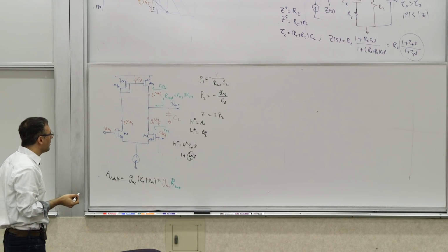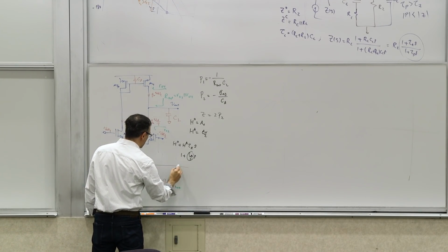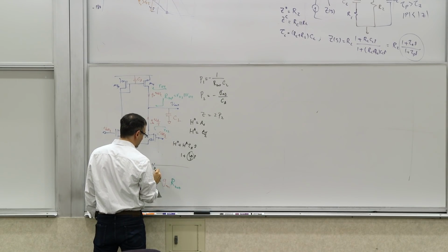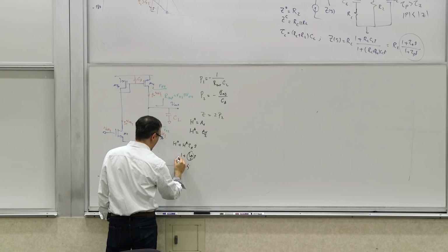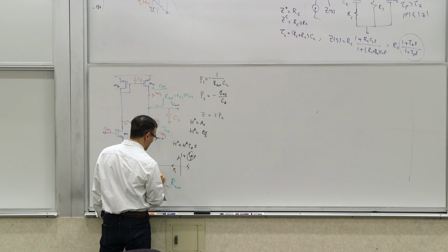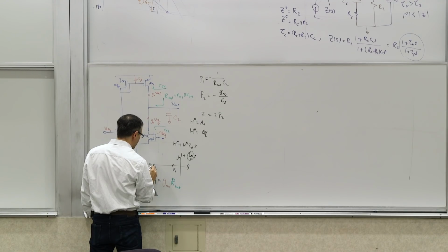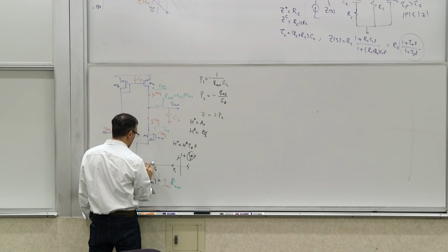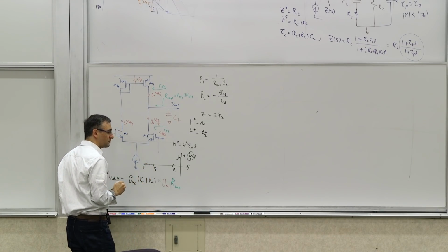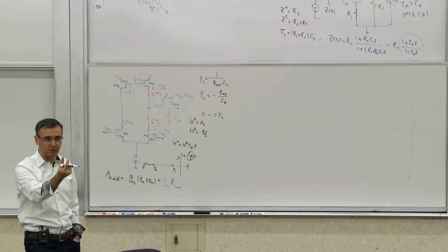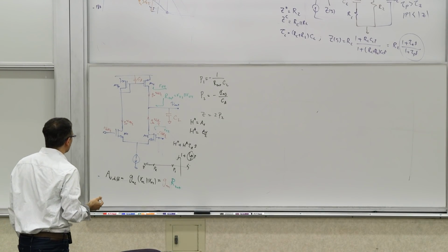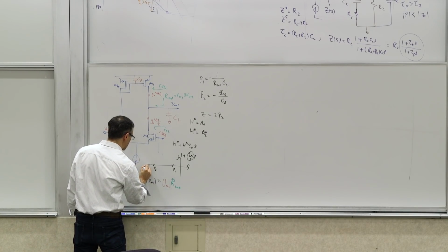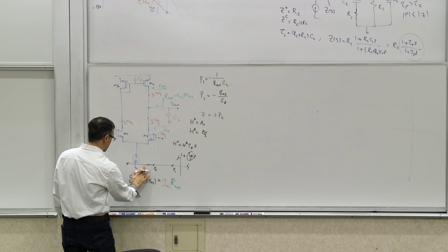So where is the pole? You can see the pole-zero constellation looks like this. If you look at the sigma j omega axis, there's a P1, there's a P2, and there is a Z, a factor of 2 behind that. If it's linear, it just looks like that. If it's logarithmic, it looks very close, not too far. This is a linear plot, so this is Z. On a linear plot, it has to be twice as far. So this is Z, really.